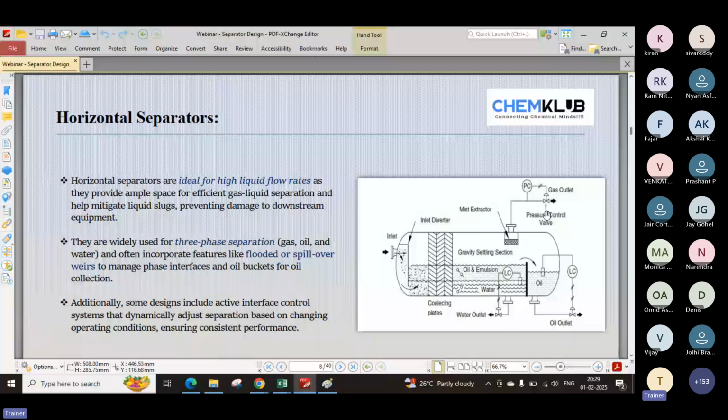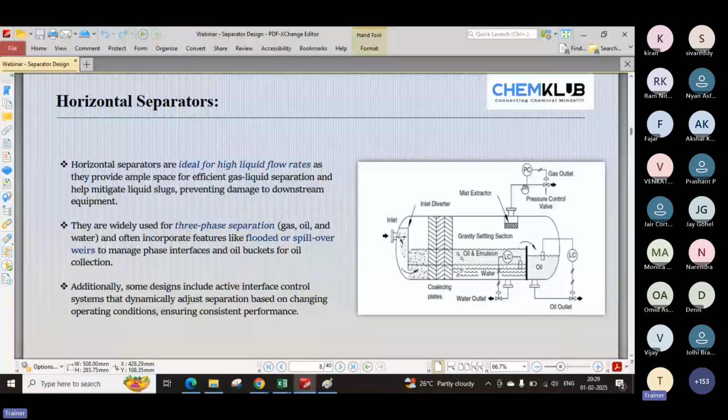It's not about the liquid volume or liquid quality or quantity. Any separator operating pressure is defined and maintained by the gas pressure. Three-phase separators are majorly used when you have very high liquid volumes or when you need clear separations. However, it has some other advantages too that we'll see.